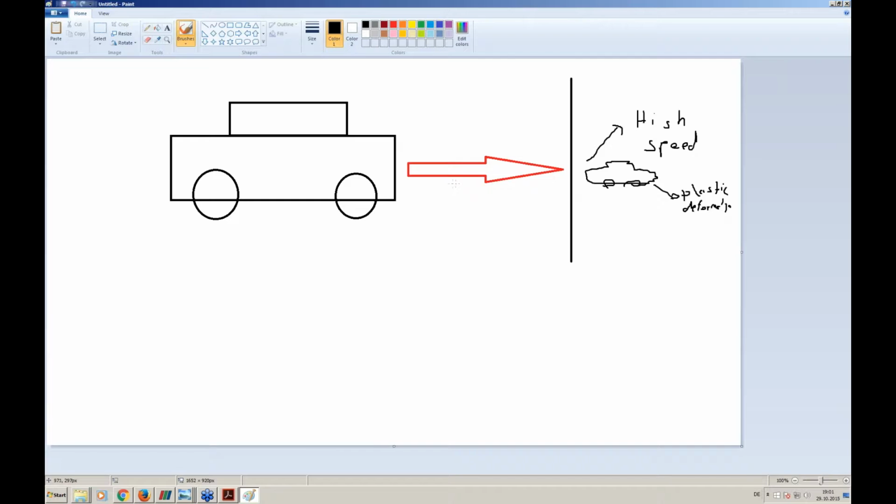So this drop testing we're using in the end is only suitable if you want to investigate small forces or small stresses, or let's say stresses and forces which are not big enough to have a really destroying impact on the material. Therefore, this kind of simulation is really suitable for our drone testing, because we want to test what is possible till the drone gets damaged. And so it's another way of setting up the simulation.